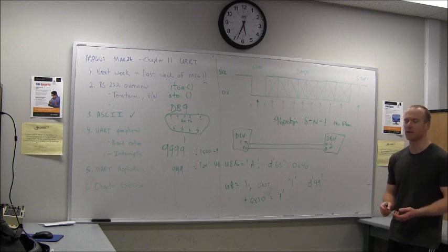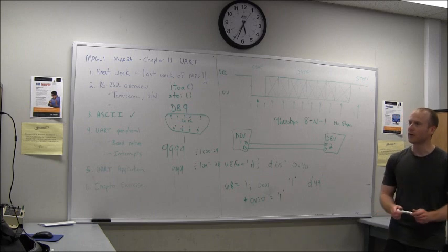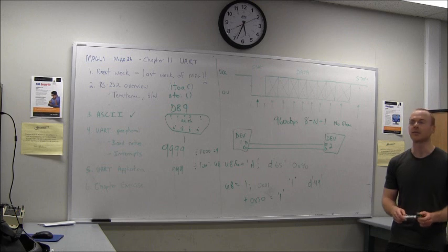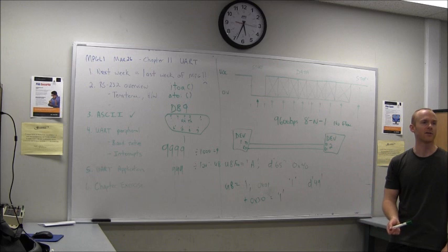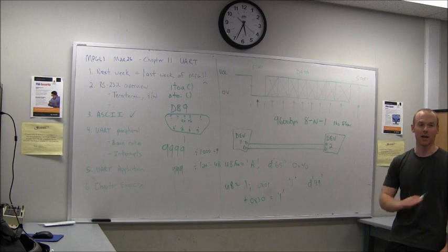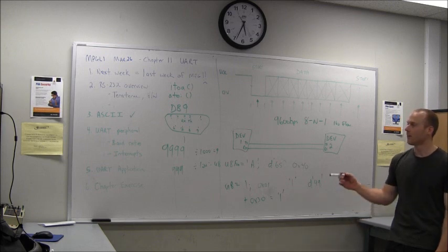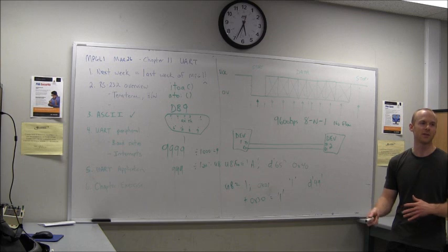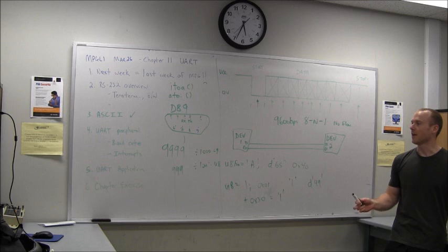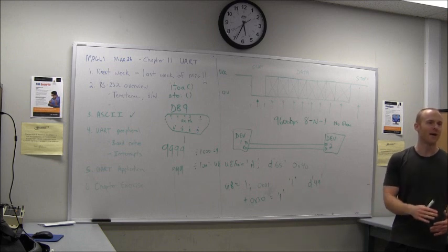The hardest part is figuring out the baud rate. There is a rather horrendous calculation to get the baud rate set. So we want 9600 BPS. We have a 12 megahertz clock source. By spec, for this particular processor, and I think every processor seems to work differently, the spec says I need to generate a clock that is 16 times faster than 9600. So 16 times 9600 is 100-something thousand hertz. And so you need to divide 12 megahertz down into that.